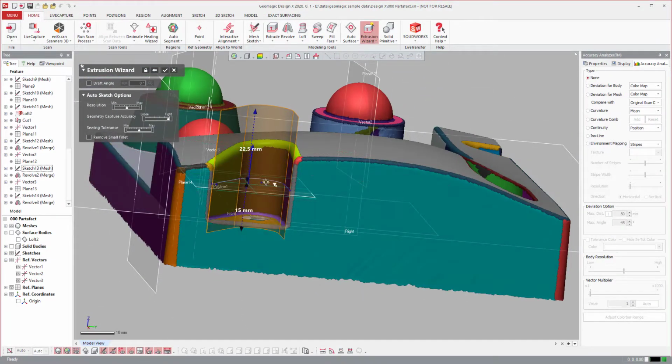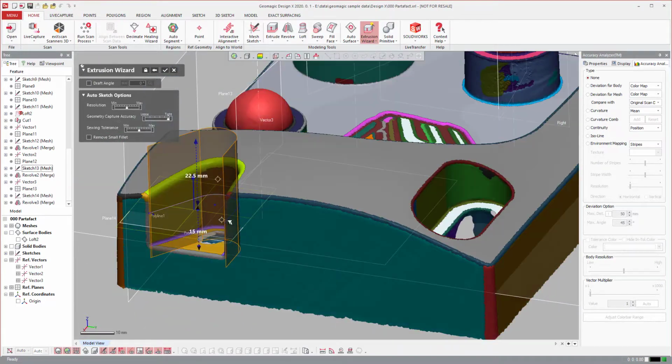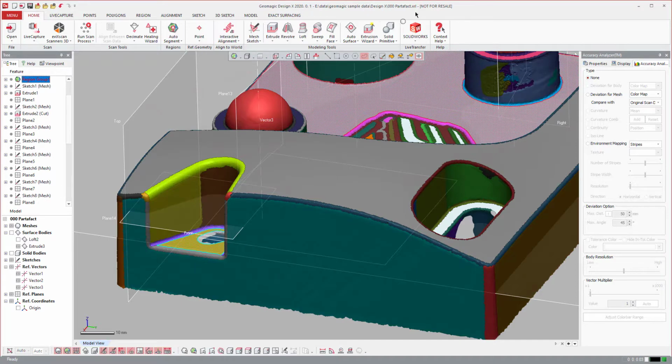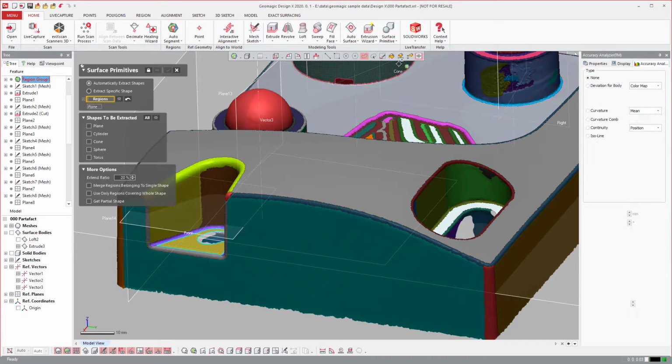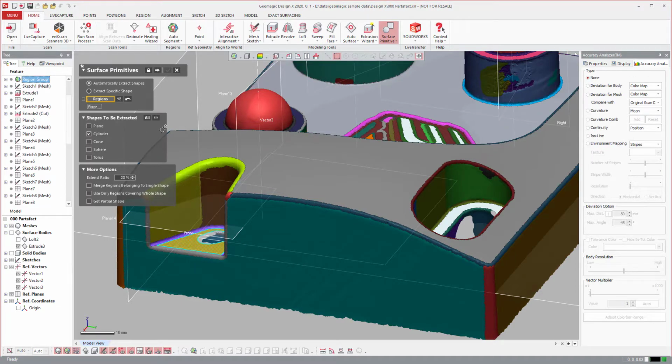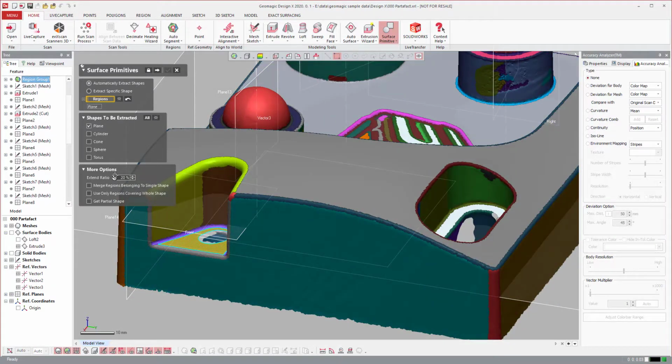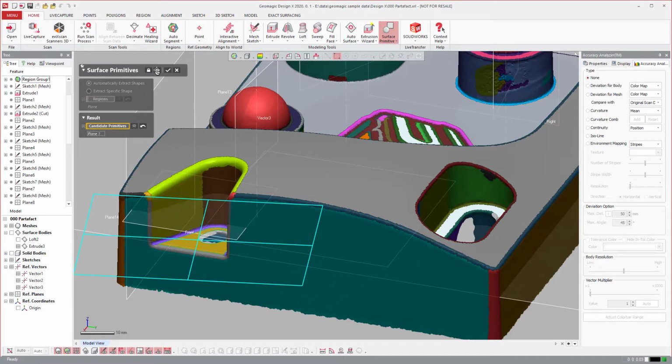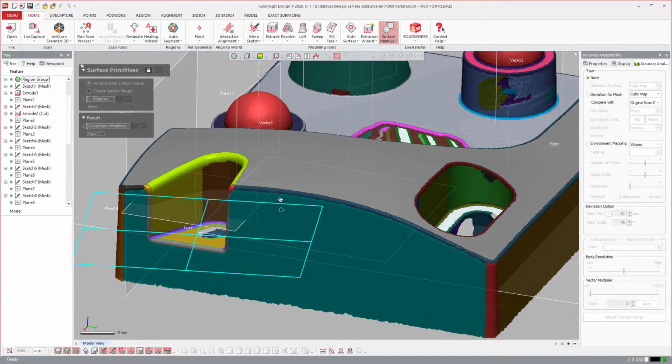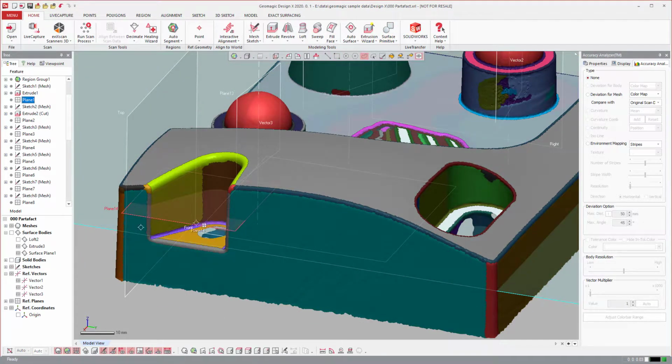You'll see that it will also do the same thing for surfaces. This is actually easier for the software to do, where I can have it model that as a CAD surface. And then the bottom, I can fit primitive surfaces. So if I say I want to fit a plane to that area, not a cylinder, I can just tell it to automatically extend. I usually extend flat planes pretty far, because it's easy to extend those without deviation. So I fit those, and again, just like before,